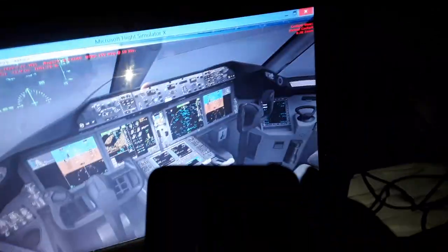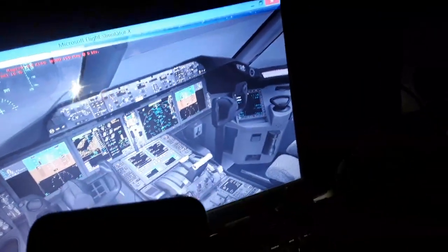So you can see here we have a few more things to note before going to takeoff. I will set up now the flight management computer, a flight one, using all the data. I need the takeoff gross weight. As I told you, the center of gravity is going to be calculated.